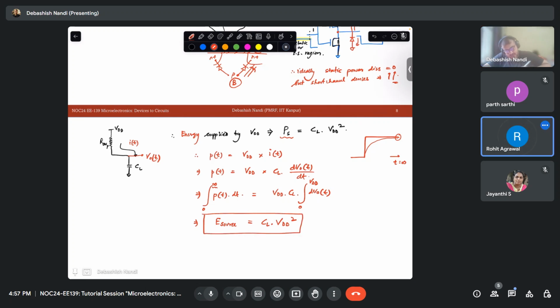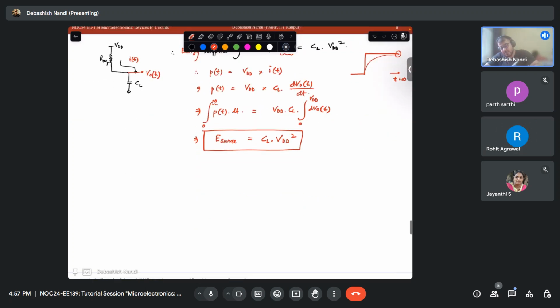Yes, sir. What you have told me is how much power is stored in the capacitor. So how do we find that? PC of t is what? Vo of t times I of t. So what is that? PC of t is Vo of t times CL dVo of t by dt.